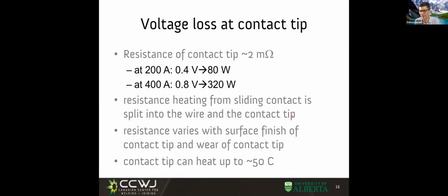If I'm welding in DC, constant current, let's say, should I worry more about the impedance or the resistance of the cables? Resistance, of course. In DC, the impedance, we don't care. But if we have pulses, we have to worry about the length of the cable.